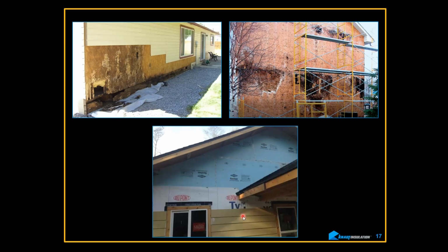This is a Habitat for Humanity house on the bottom. Problem is, if you haven't already spotted it, the WRB is in the wrong space. So this is a semi-impermeable material. Some people call it impermeable, but it really doesn't let enough moisture out when conditions are right. This should be a wrinkle wrap, a drain wrap, or something with a texture to it to create a capillary break, and that goes on the sheathing, taped, sealed, nail spotted, everything, cap fasteners, do it right.